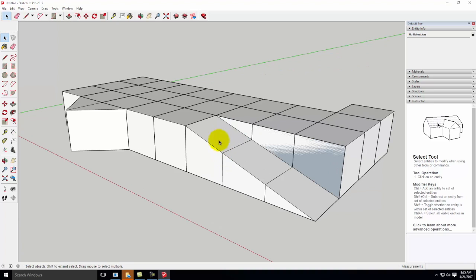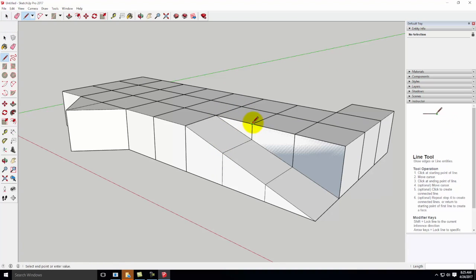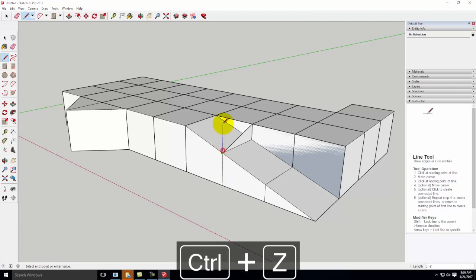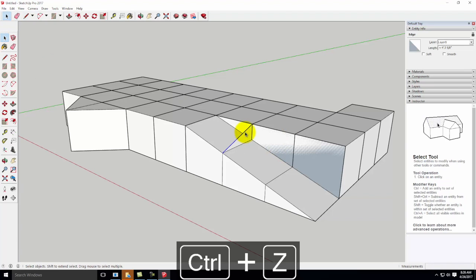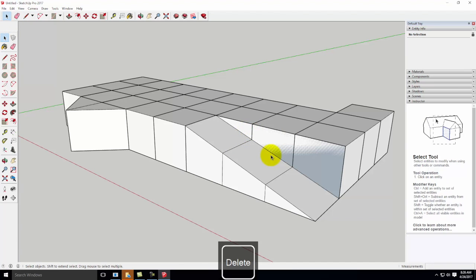Sometimes you do get curves that are out of plane. So for example, if I drew a line down here, I have four curves, but they're not in the same plane. In order to make a surface, I would have to divide this either that way or that way. So sometimes you end up with a surface that just doesn't quite work, and that can happen.